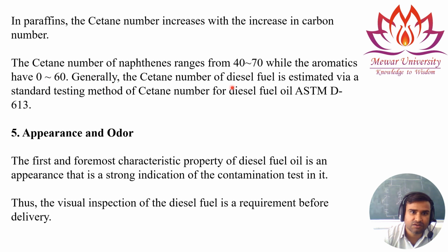Generally the cetane number of diesel fuel is estimated by the standard testing method for cetane number of diesel fuel, and that is ASTM D613. So overall, the cetane number should be higher, and the percentage of carbon should be lower, so that the engine does not knock.